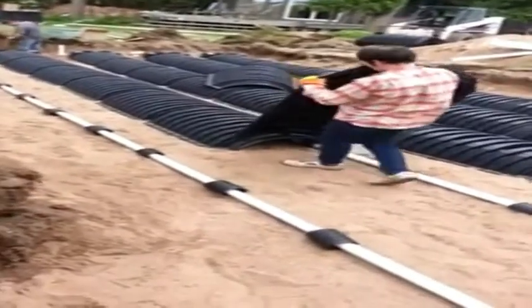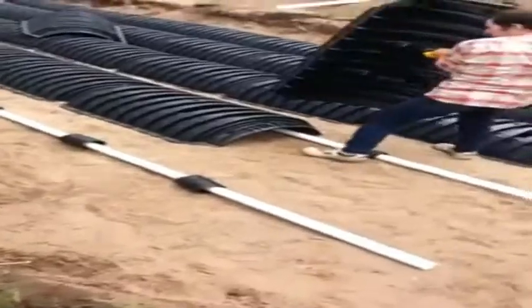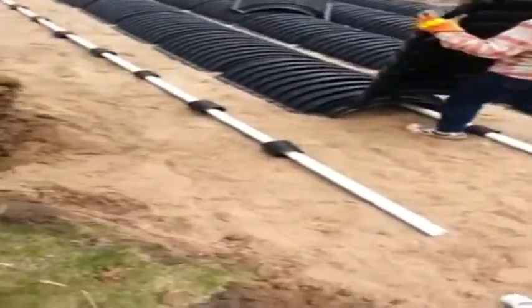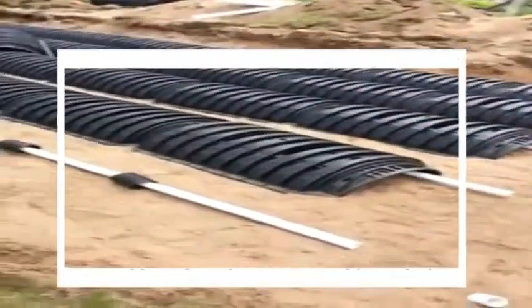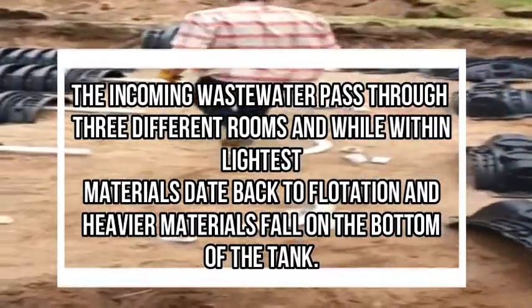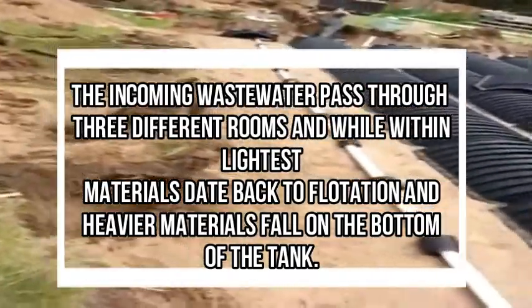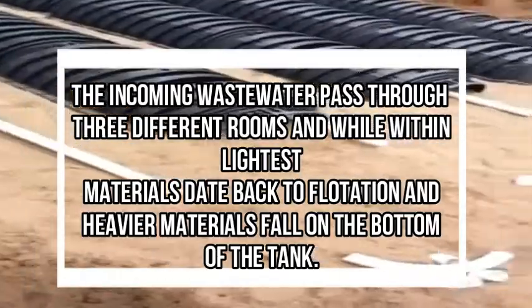The septic tank with 3 chambers works by gravity separation of foams, fats and sludge. The incoming wastewater passes through 3 different rooms, and within them the lightest materials rise to the top by flotation, and heavier materials fall to the bottom of the tank.